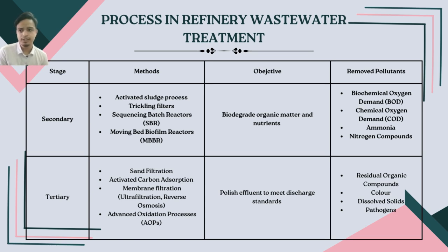For the tertiary stage, the methods used are sand filtration, activated carbon adsorption, membrane filtration, which includes ultrafiltration and reverse osmosis. And the last method is advanced oxidation processes, AOPs.